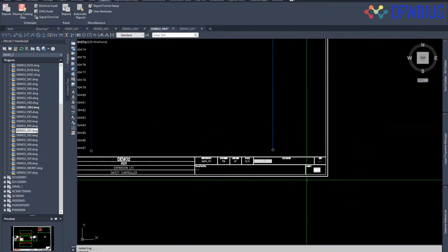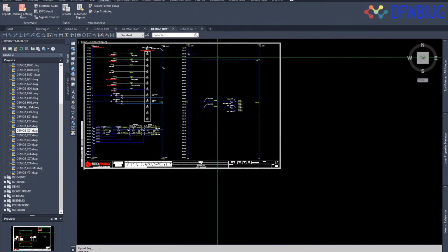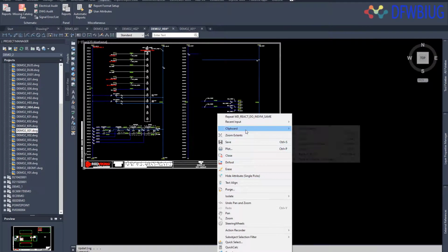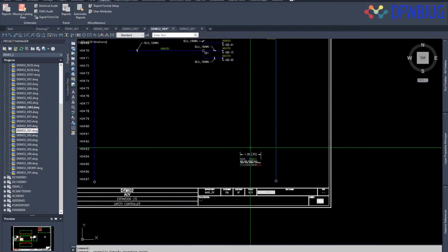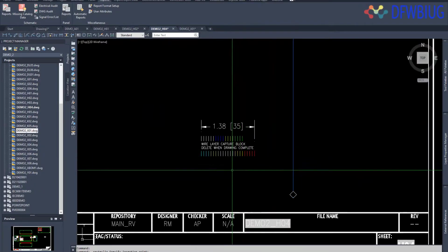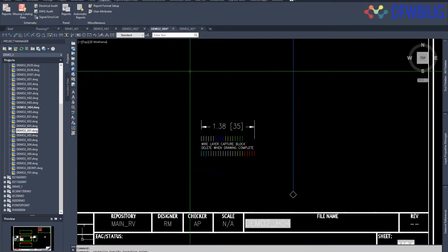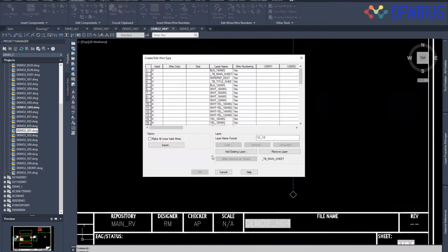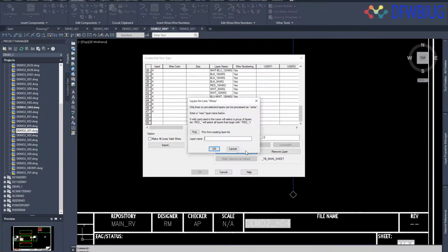Now, what I have just done is I want to put wires in here, but you see I only have blue 16 AWG, for example. Let's do this. This block, when put into a drawing, brings in every standard wire layer I have and my dimension styles. Now, if I want to create a particular wire type, you see all these new wire types that came in because this block captures all of those layers.